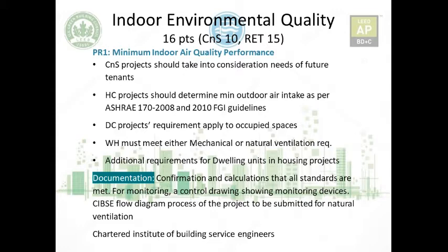So this is the prerequisite, and for the documentation we have to confirm and calculate that all standards that we have seen for the regular ASHRAE 62.1-2010, and for healthcare, these additional standards are met. And for monitoring, a control drawing showing monitoring devices for natural ventilation, if you have CO2 sensors, or if you have exhaust airflow sensors, and all the required devices.